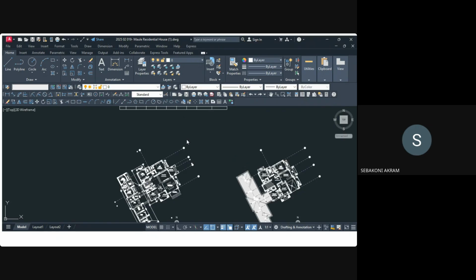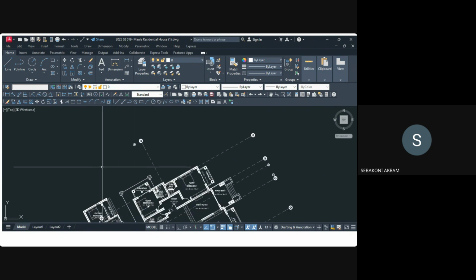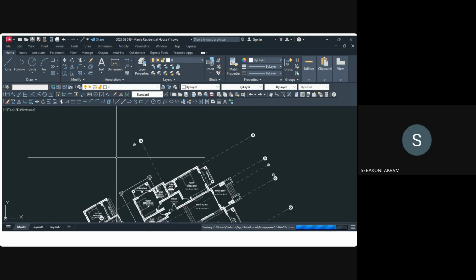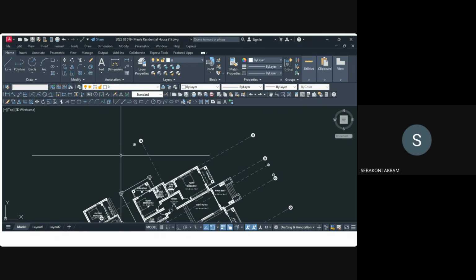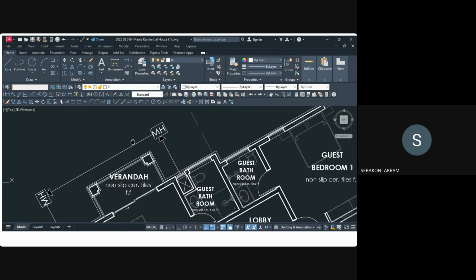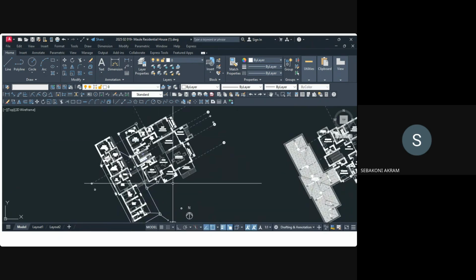The architect imports his drawing from AutoCAD or Revit, and it is still aligned in layers. If he or she gives you a PDF, it will give you complications in the cleaning process. So that's why it's more preferable to have the DWG. However, if the PDF is the only option, then you go with what the customer needs, because at the end of the day, you'll have to satisfy the customer's needs. So for that case, we're going to first delete all the unnecessary information here.